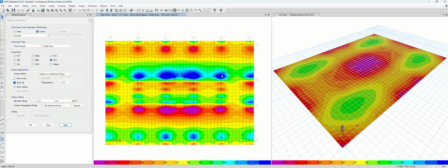When you add the gravity effect and the coupling overturning induced compression forces, it's going to create more shear stress. So we need to consider maybe partially increasing the thickness in the middle zone or some shear reinforcement.